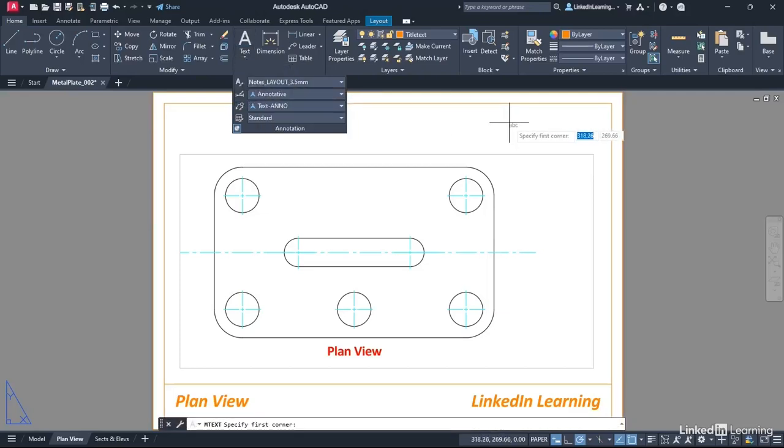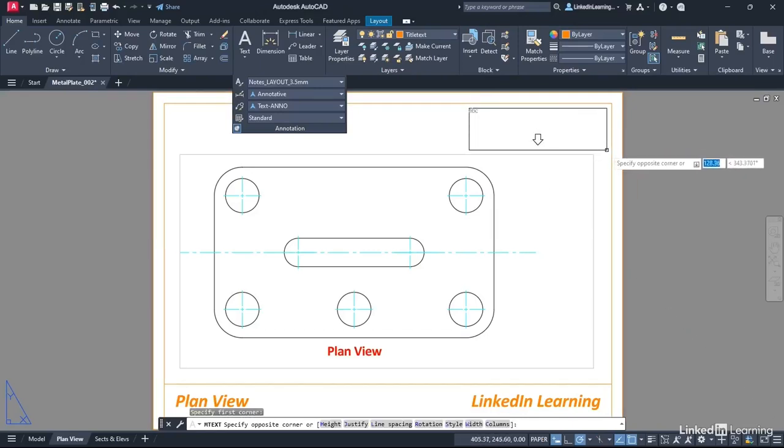And then it's like placing a rectangle now when you place multiline text. Multiline text occupies a space. It's not just a single line text object. So I'm going to click here. Make sure you don't get any object snaps, otherwise it will snap to say the midpoint or the end point. So click, drag the area where you want the text to go. Get it as close to that edge. See that endpoint snap? Just move back a little bit so that endpoint snap doesn't highlight, and click again.